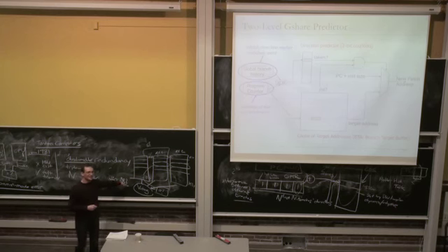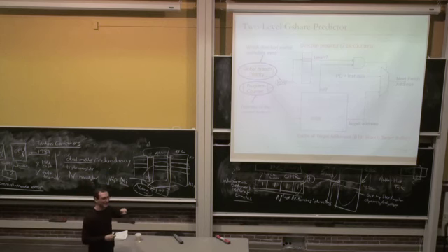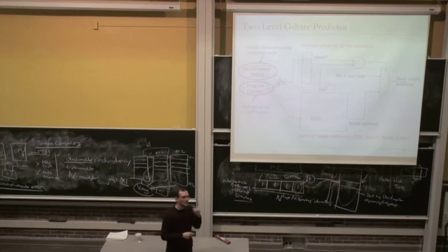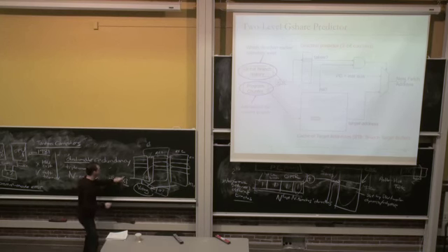Well, that depends on where you access the register file in your processor, right? If you access it very close to the fetch stage, then you'll have some bubble, right? But when we cover out-of-order execution, you will see that there could be like 20 or 30 stages, plus the data could be dependent on some cache miss. So it could be hundreds of cycles until this data is available. Okay? In a very simple pipeline, if you access the register file the next cycle after you fetch the instruction, then branch prediction doesn't help you that much, right? Indirect branch prediction. Okay.